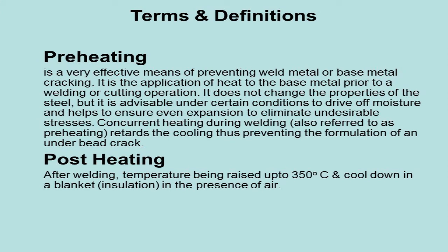Preheating is a very effective means of preventing weld metal or base metal cracking. It is the application of heat to the base metal prior to a welding or cutting operation. It does not change the properties of the steel, but it is advisable under certain conditions to drive off moisture and helps to ensure even expansion to eliminate undesirable stresses. Concurrent heating during welding, also referred to as preheating, retards the cooling, thus preventing the formation of an underbead crack.